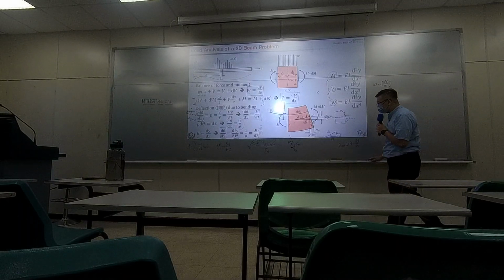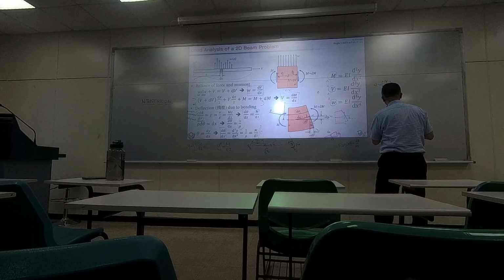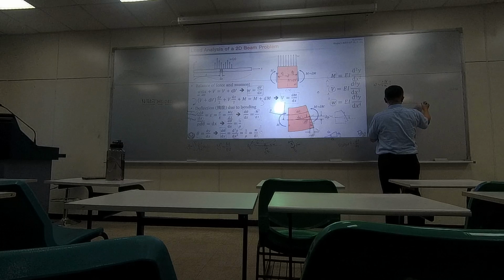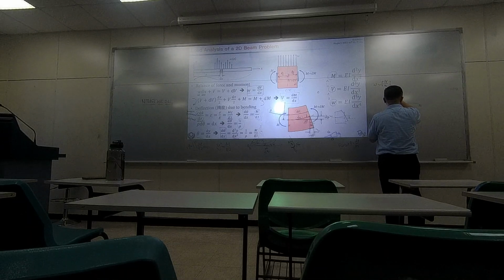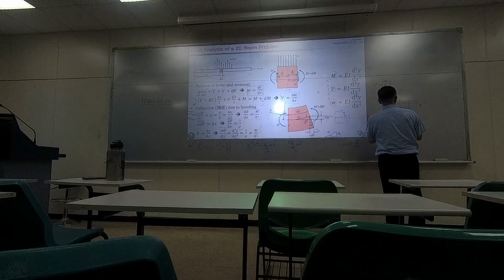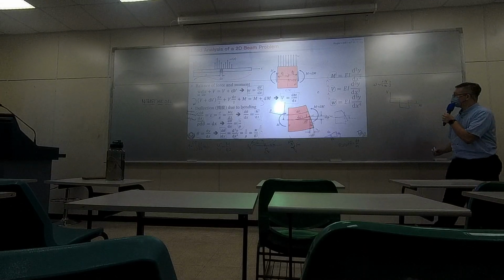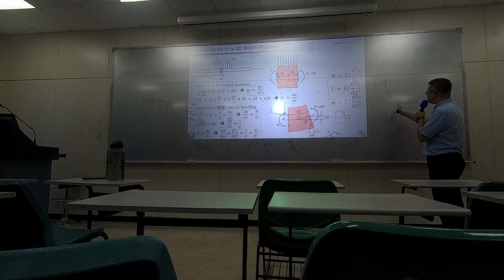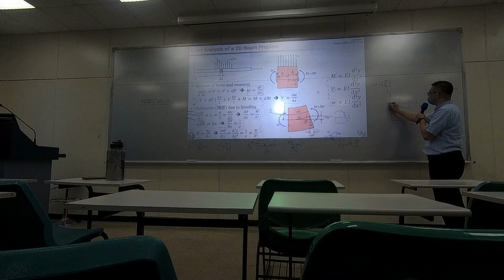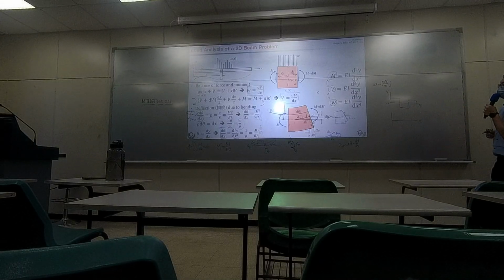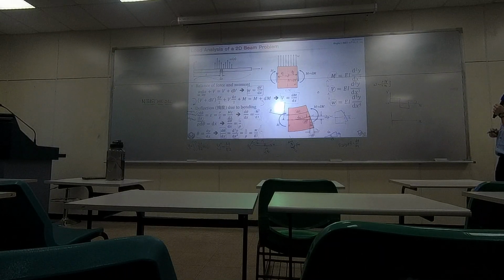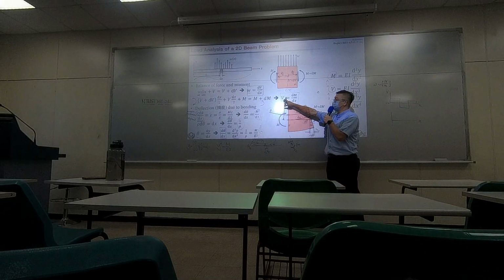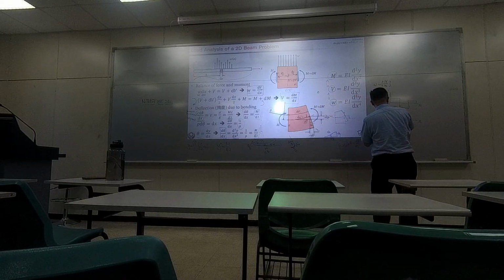Okay? So for a beam problem, what's the usual process? We figure out a shear diagram, so maybe just randomly, some shear diagram. Once you have this shear diagram, you figure out the shear force. This is V equals 0. You know the shear force everywhere. What can you do next? You can take the integral of V. Then you get M. So this is the moment.